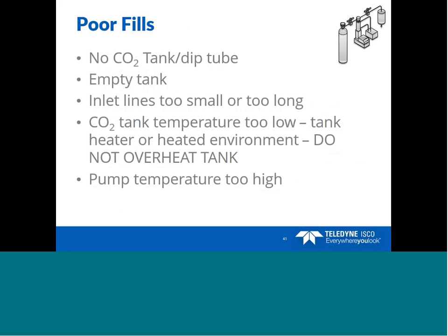Poor fills can be caused by no CO2 tank dip tube, an empty tank, or inlet lines that are either too small or too long, which create unnecessary restriction. Another cause is CO2 tank temperature too low, which causes the vapor pressure to drop. This can be resolved by adding a tank heater or putting the tank in a heated environment. But be careful, do not overheat the tank.